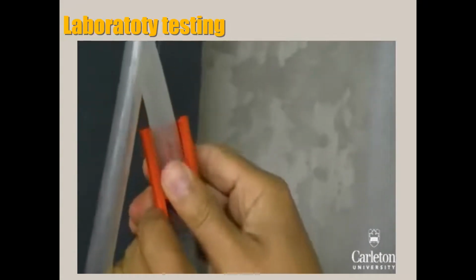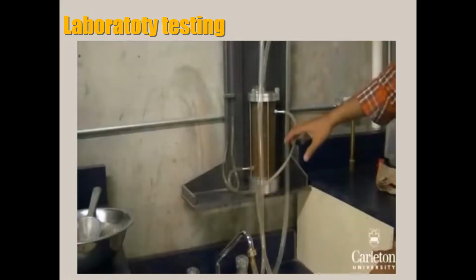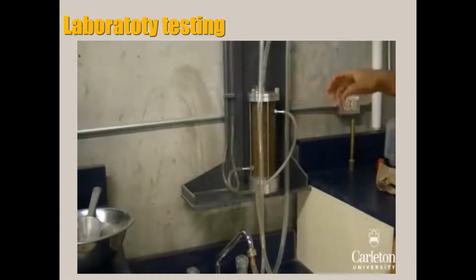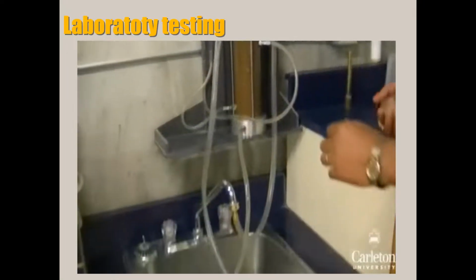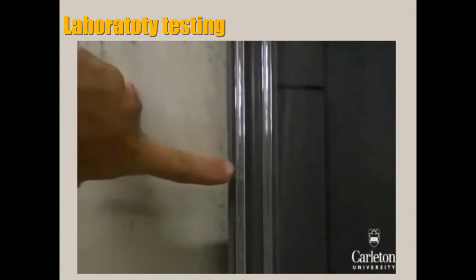Now open the valve to let water into the sample. Before we start measuring flow rate, we need to let water run through the sample. This is to remove any trapped air. Let the water run through the system for a few minutes. Here we can see the pore water pressure being recorded on the 2 manometers.